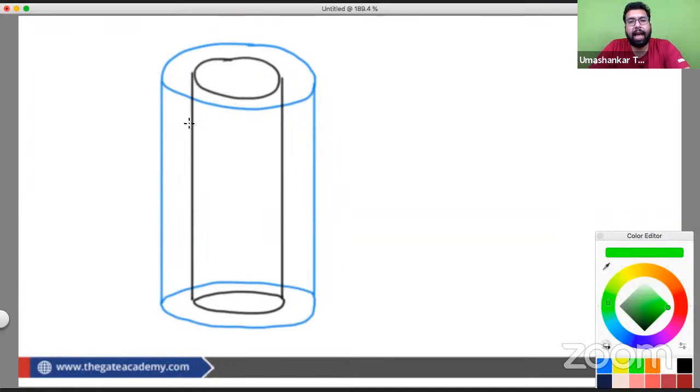When we have this cylinder inside it rotating at some velocity, now tell me one thing, whenever some circular cylinder is being rotated with some velocity, does it have surface velocity or not? That we generally know as r omega or pi D N by 60. Please tell me yes or no, beta. Is it fine to you guys or not?